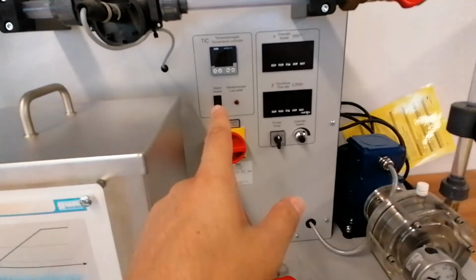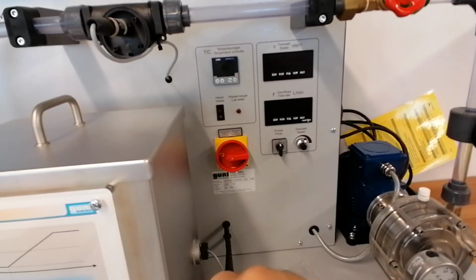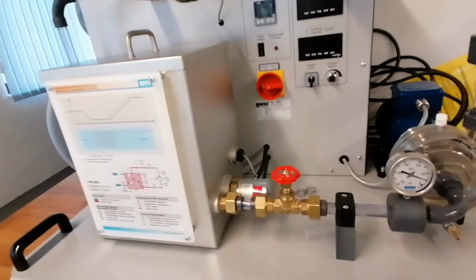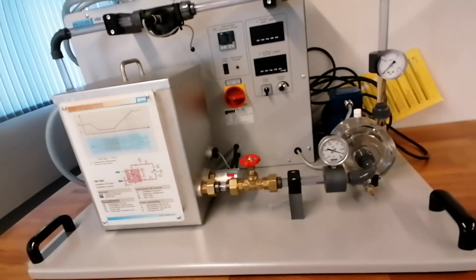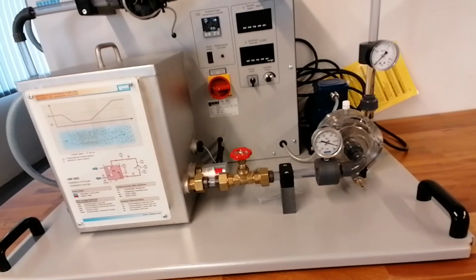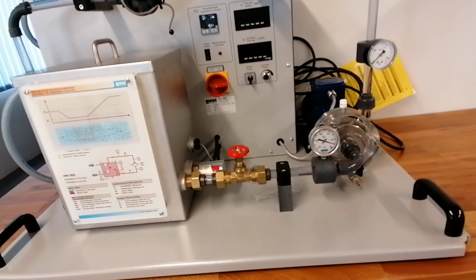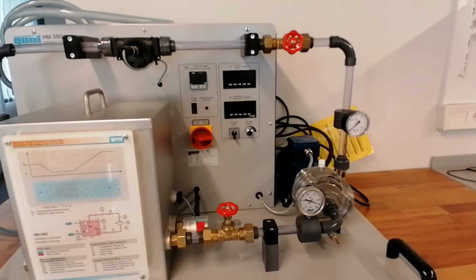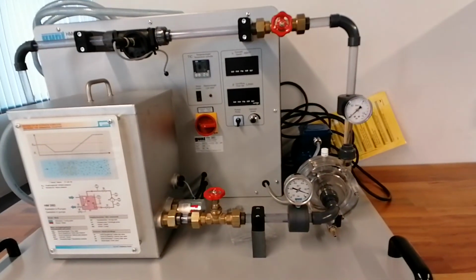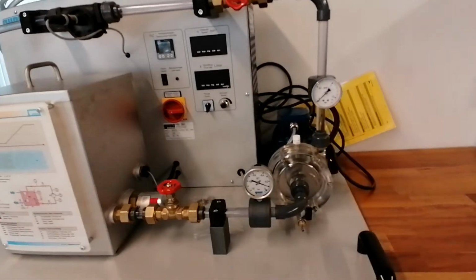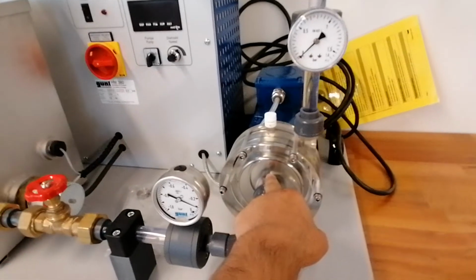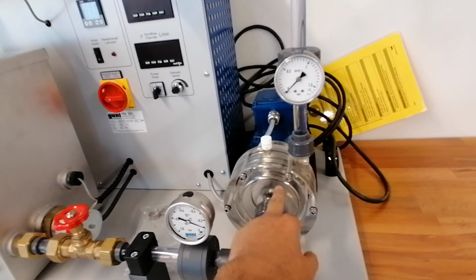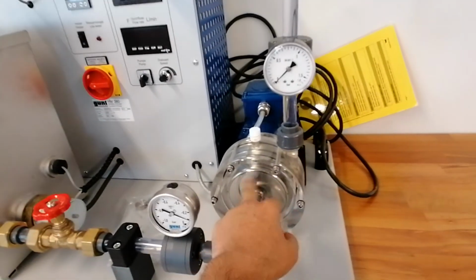So I can say that increasing temperature increases cavitation. And also by increasing velocity, you will see that cavitation will increase, and you will hear high levels of sound, and see cavitation bubbles. From here you can see it is transparent, so you can easily observe the cavitation bubbles there.